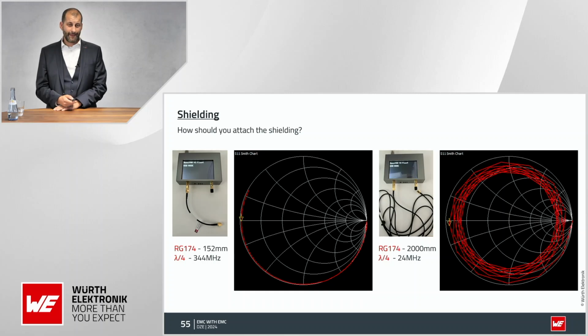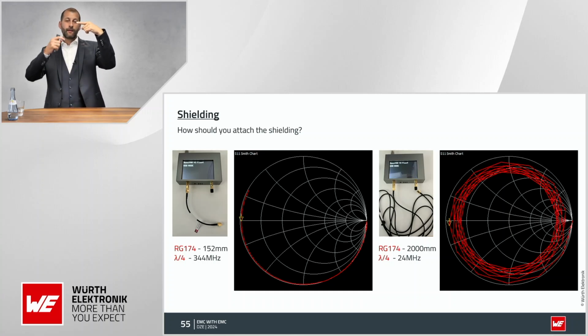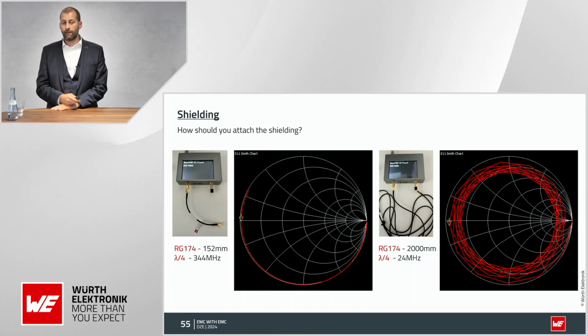Well, you have an inner conductor, you have in this case a capacitance, you have an inductor. You also have, due to your shielding, a capacitance. So what did you create? Well, a low-pass filter. In this case, for the customer, it was ideal because that low-pass filter was filtering out all of that noise.